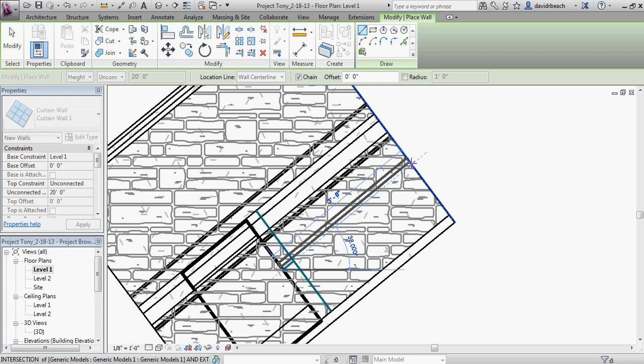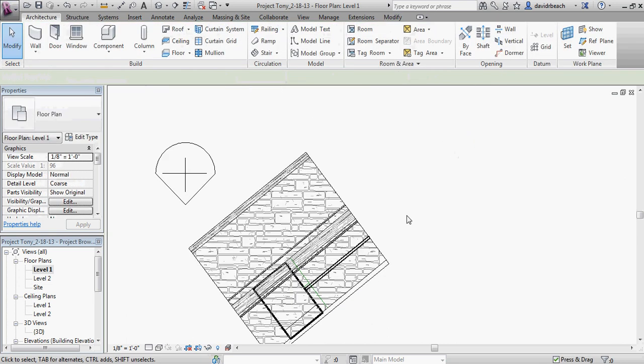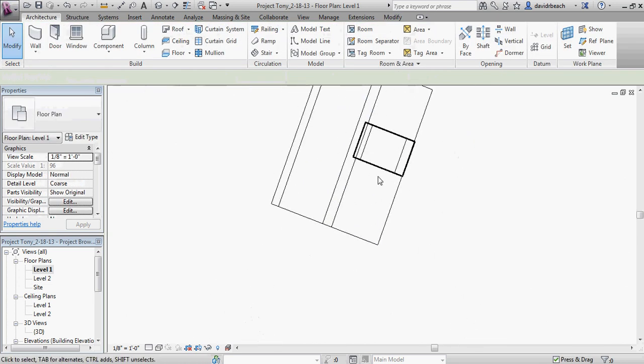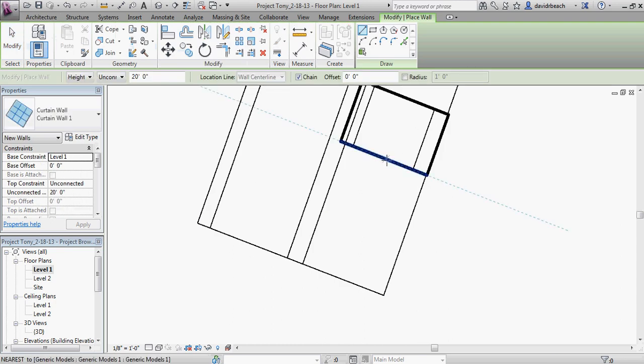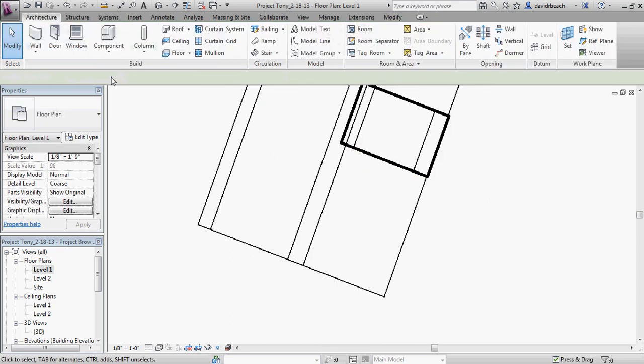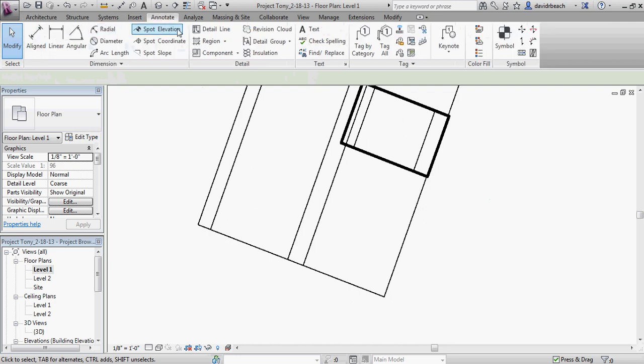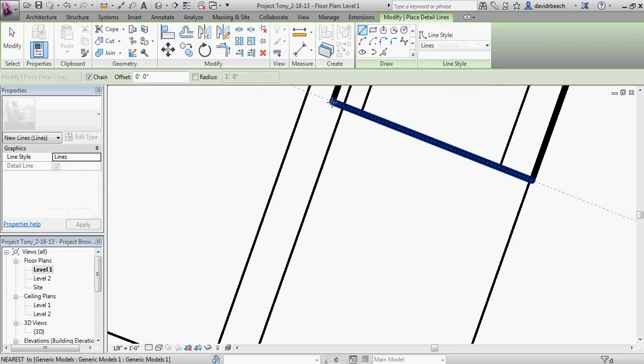So I'm going to my curtain wall, that midpoint line, and I want that glazing to happen to the outside edge of my midpoint line. So I'm going to snap from here to here. I'm going to do the same thing from this element over. Again, I'm going to have to build a quick guide for that so I can locate the midpoint of the column.